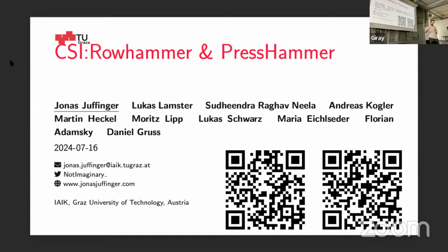So if you reduce the voltage to a level where it works now, of course, there's no guarantee that it will work next year. So what these manufacturers did, they didn't decrease it to the absolute minimum where it works straight out of the factory, because then every phone would probably break after a year. But still, they did stuff like that. One pushback for those works was that you do this characterization once, you find out the guard band, it's the guard band today, and then tomorrow it can be a different guard band. The characteristics can change. This is why they put the huge guard bands.